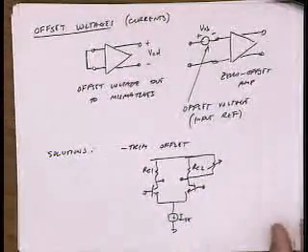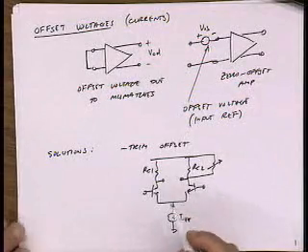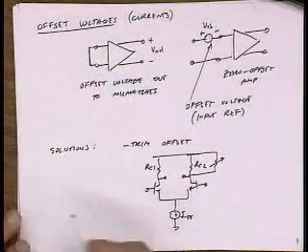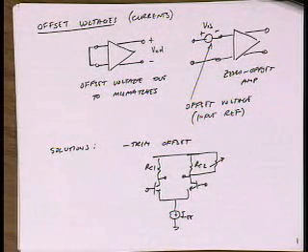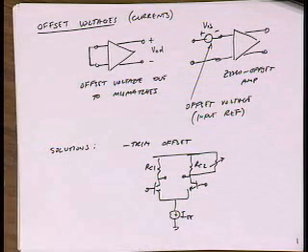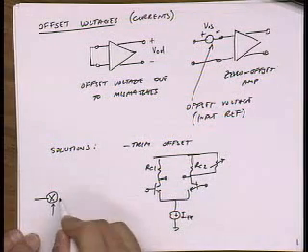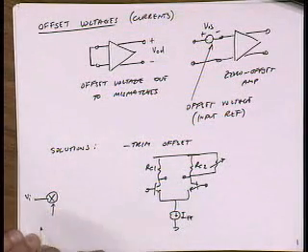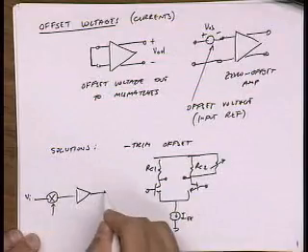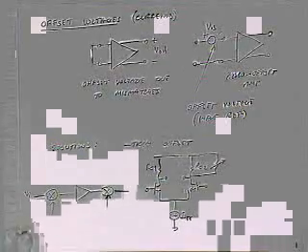But just for those of you who may be interested, let's say you're trying to amplify a DC signal. Well, you could modulate it up to a higher frequency, go through your amplifier, and modulate it back down. You think, oh, that's ridiculous. You need two mixers, and now your mixers have to be precise and everything. But do you really need mixers for that? Anybody think of a way of avoiding mixers? So here's the idea. I'm going to take my input signal, mix it to some higher frequency, go through my amplifier, and then mix the output back down to a lower frequency.